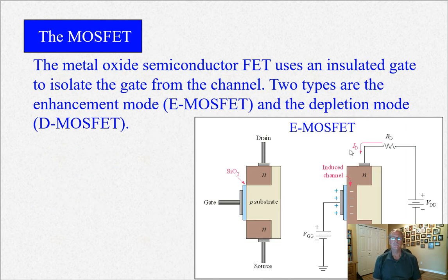Okay, so that's JFETs. Let's move on to MOSFETs, metal oxide semiconductors. It's the same idea, okay? In other words, it has a gate, a drain, and a source. And the gate current is minuscule still, all right? But they're used normally for more high power applications, okay? Amps to hundreds of amps, although there's much smaller ones too.